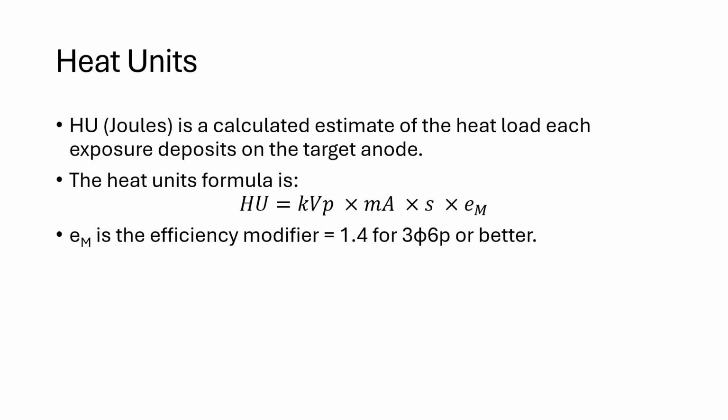So the 3 that I had to learn was 3-phase 6 pulse is actually 1.35. 3-phase 12 pulse is 1.41, and then high frequency is 1.45. And these are all root mean square voltages versus full wave rectified voltage. But if you take 1.35, 1.41, and 1.45 and you put them on a number line and then you go to the other side of a long hallway and you kind of squint, those dots are really close together around 1.4.